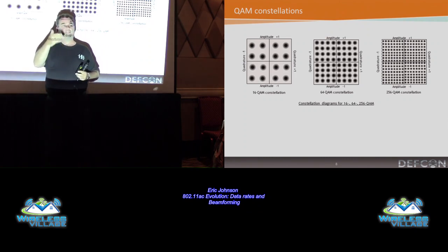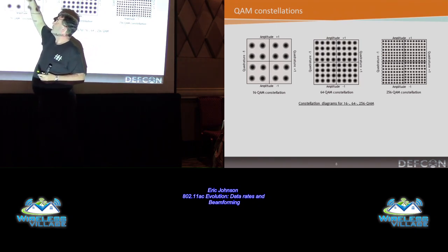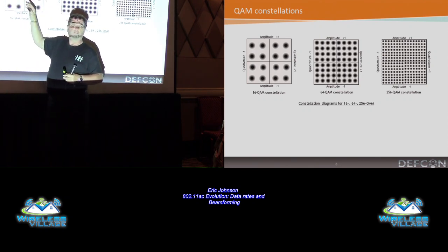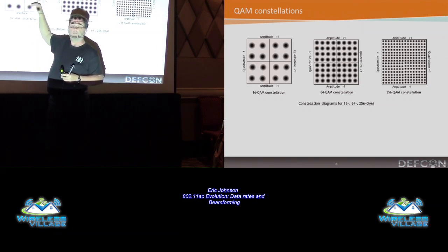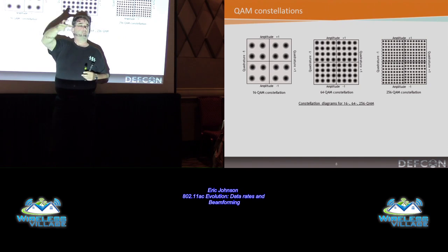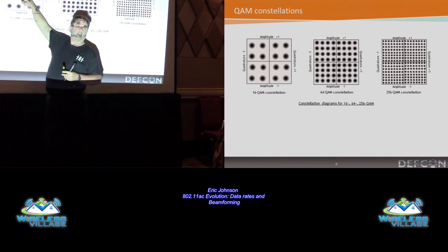So on this burst, I'm going to send these 4 bits to create this symbol. And what those 4 bits are encoded, literally, the first bit tells you top and bottom. The second bit says left and right. So, okay, after the first 2 bits, maybe we're in this quadrant. Then the third bit's the same thing, left and right, 4th bit, top and bottom. So finally, maybe the symbol will create that position on the constellation. So for the duration of one burst, we will be sending that amplitude and that phase.